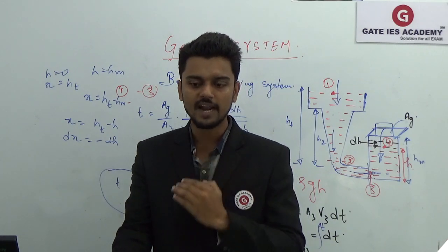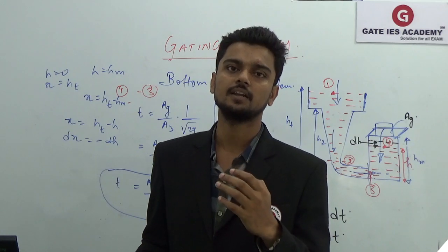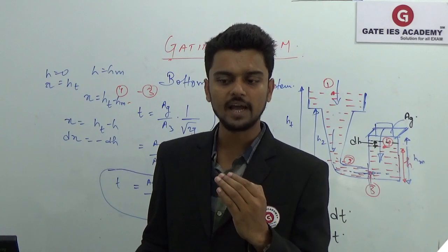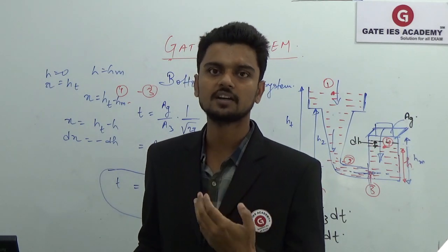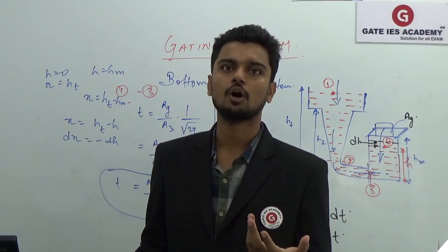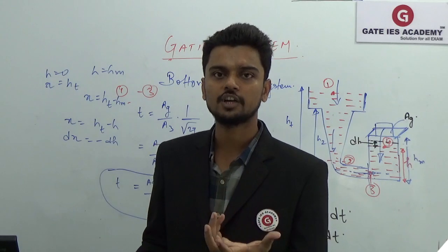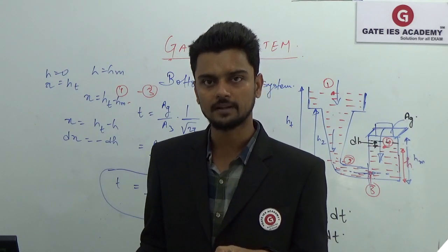So in that case again we are avoiding the unfavorable temperature gradient. Unfavorable means it started solidifying, say, from the top, so the riser will not be able to feed because the molten metal has already solidified at the top. So it will restrict the flow of that molten metal.